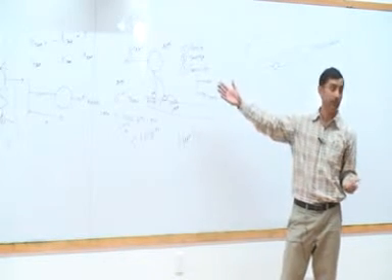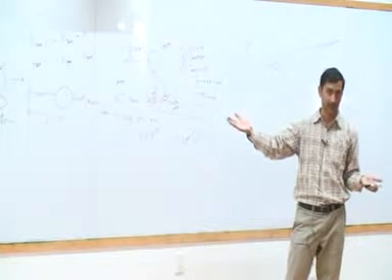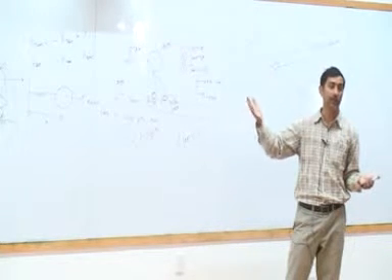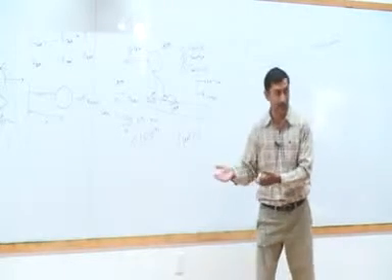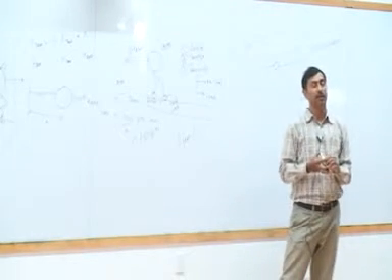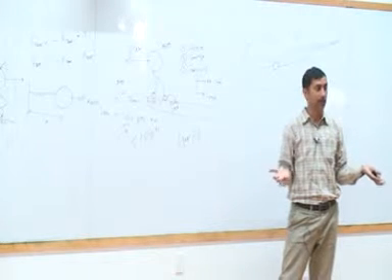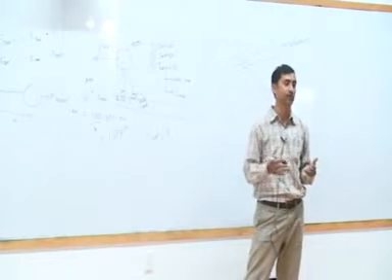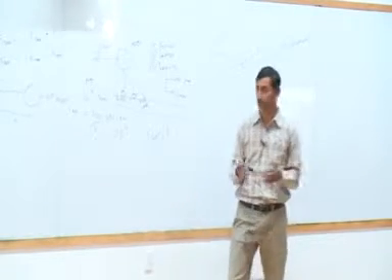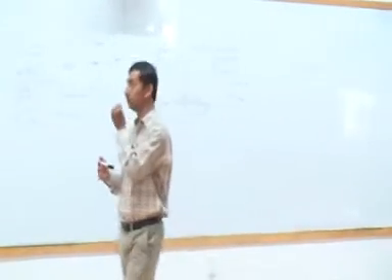Now to detect that, you need something which is faster than milliseconds. So the rate at which you sample the position of this object, for example, in this application, has to be in kilohertz, right? Kilohertz or more. So typically you sample at a few kilohertz. Then you are sure that you've caught everything.